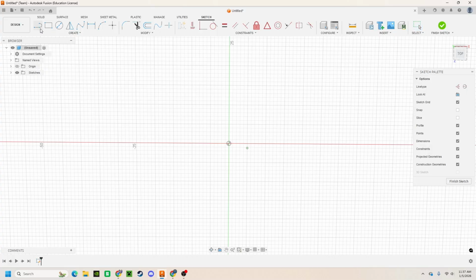If we take a line like this, it is not defined at all, since we can move it around. Its angle is not defined either, since we can change its angle, and of course its length can change as well. If we apply the fixed constraint, it will lock it into place, except for the length, though we can lock the endpoints to make it fully constrained.